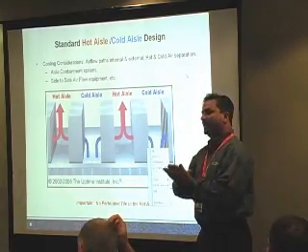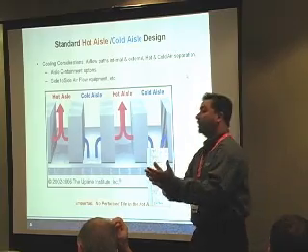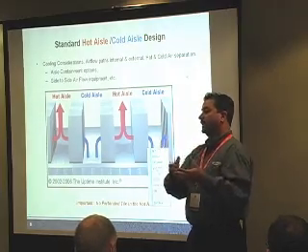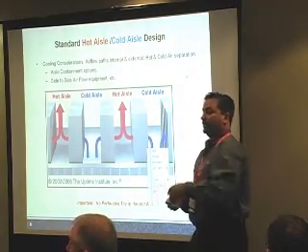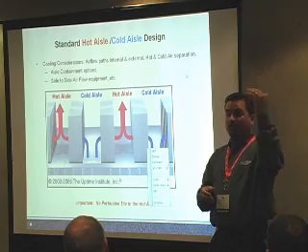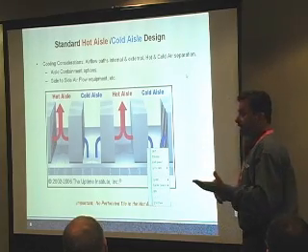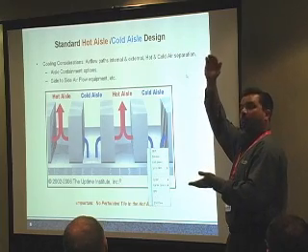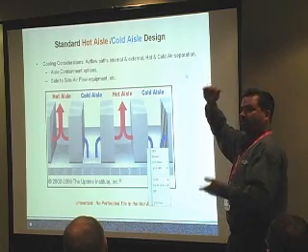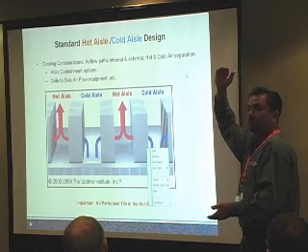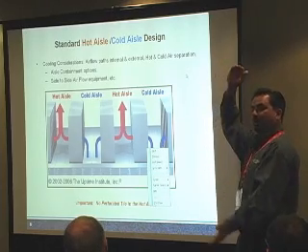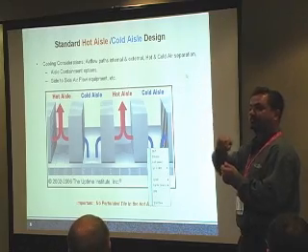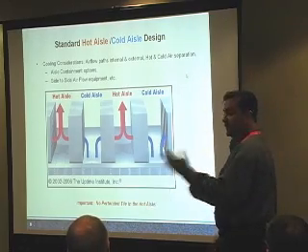Well, like I said, every data center is different, so we have to evaluate what your room is, where your CRAC unit is, and what's the best way to get it to your CRAC unit. Via just a chimney where it doesn't go into it. We're making a data center now where the chimney is just 5 feet high, just to get that up and above the air intake, because they have an 18-foot ceiling. So we're just trying to get that away from the air intake and get it directed to the return. So each one is different.